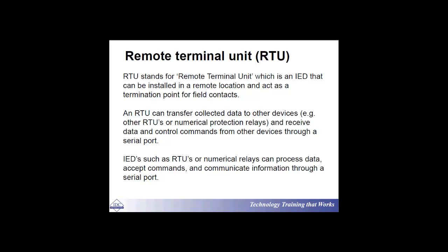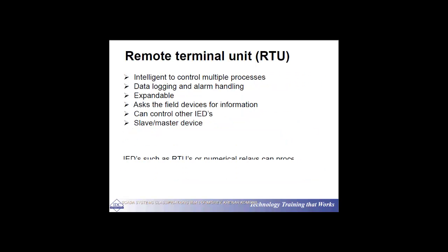So that's how it works. Therefore, what is an RTU? A SCADA RTU is a device that is intelligent enough to control multiple processes. So it is not just connected to one CT or one VT or one sensor. It should be capable of doing data logging and alarm handling if required.